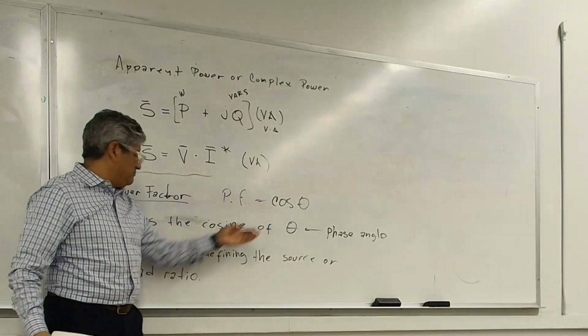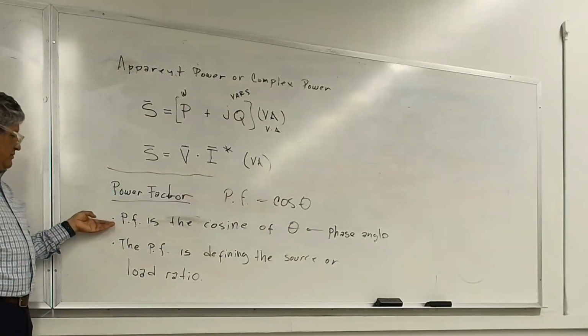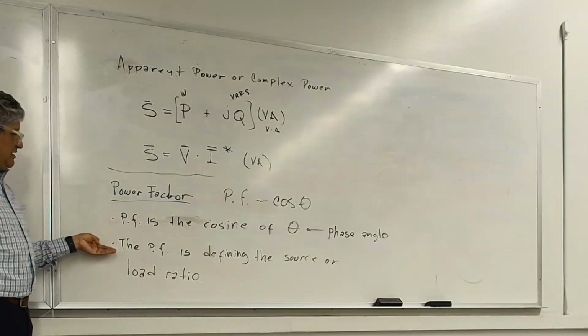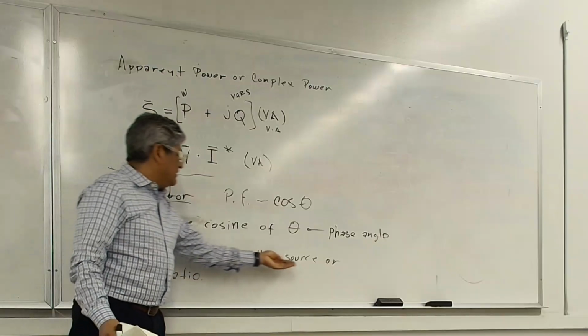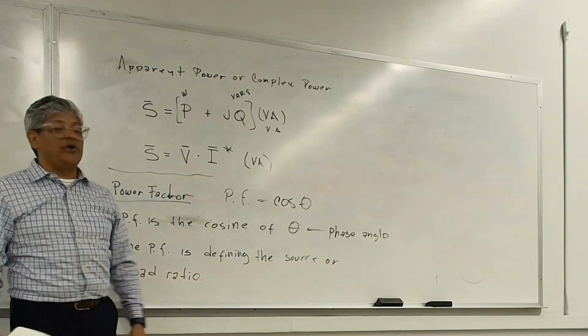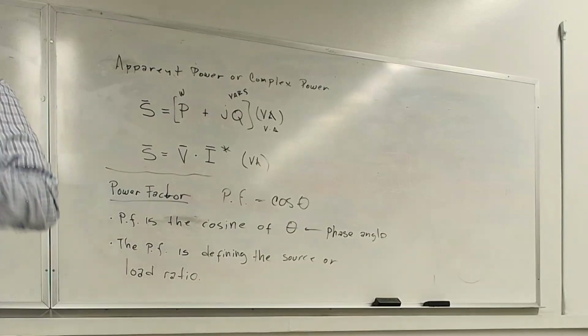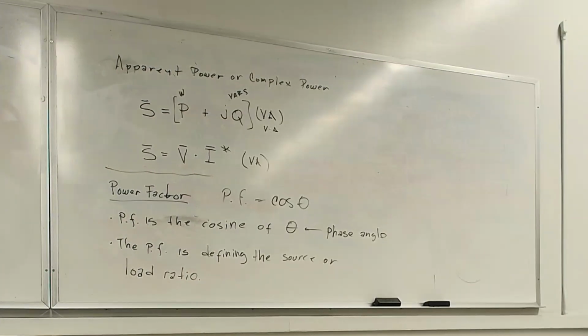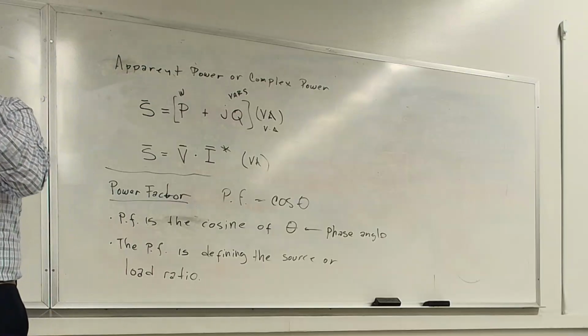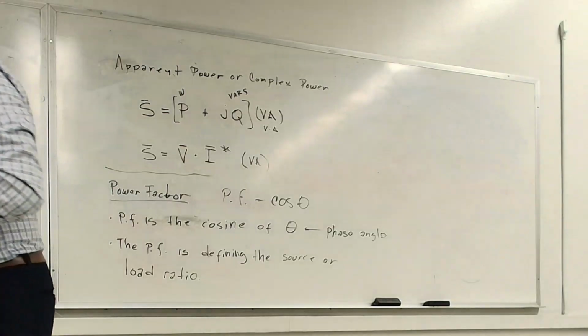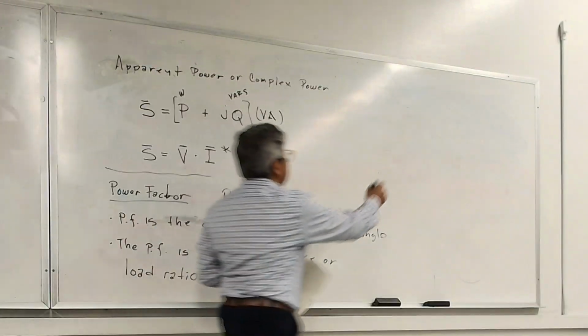Whatever value it gives you, that is the power factor. Furthermore, it defines the source or the load ratio, meaning the power factor tells you the ratios of real, reactive, and apparent power that the source is supplying and that the load is absorbing.